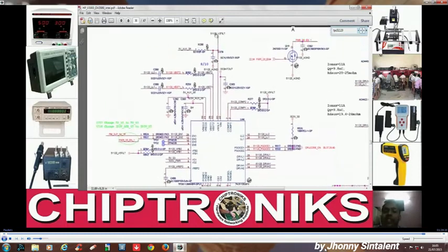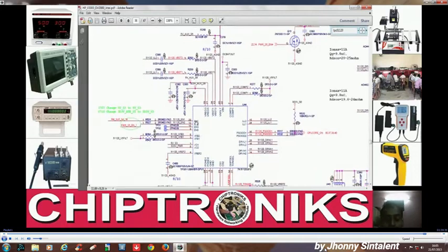So if this IC gets the DC bat out, then V regulated 3 and V regulated 5 will turn on, and here you can measure with a multimeter 3.3 volt and 5 volt. And if you're not getting 3.3 volt, check these two pins, enable 3, enable 5, whether they are getting to ground. If not getting to the ground, then your IC is faulty.